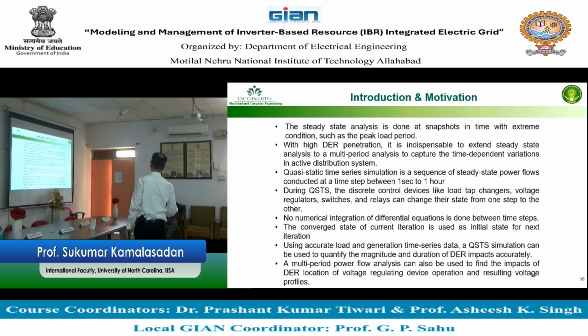Using accurate load and generation time series data, QSTS, quasi steady state time series simulation, can be used to quantify the magnitude and duration of DER impact. Now you understand the difference between time series power flow and the normal power flow? Yes? Okay.